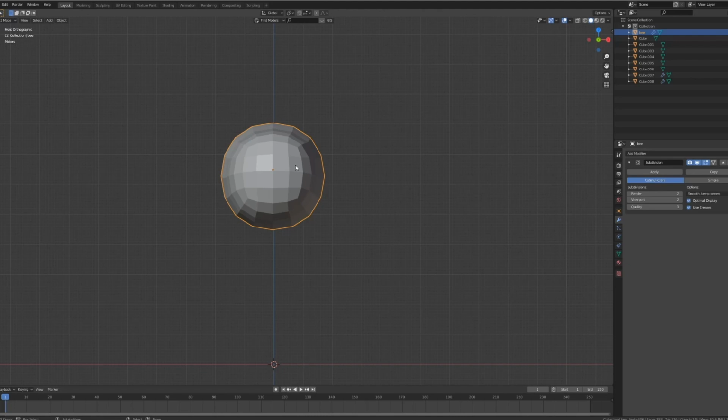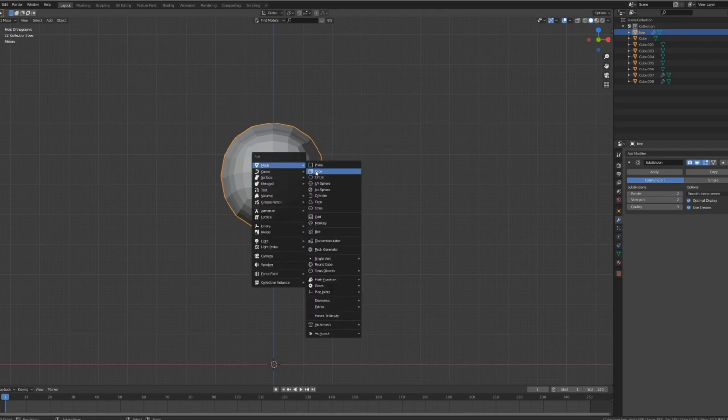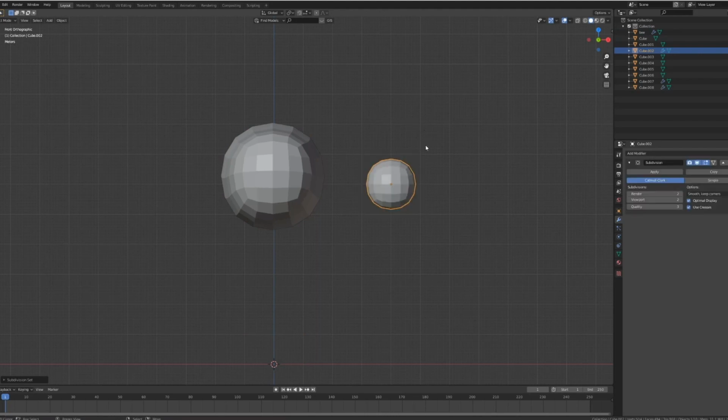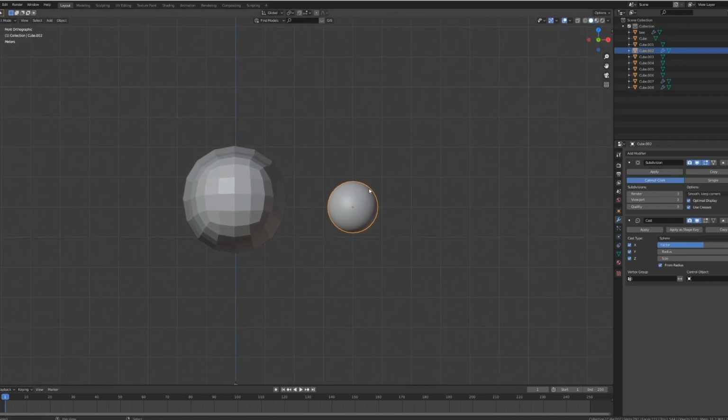Now we're going to go into the thick of it. So we're going to create a cube. I'm going to add a cube. I'm going to subdivide it with Ctrl+2, so I get multiple subdivisions. I'm going to increase the render and viewport to 3, and I'm going to add a cast modifier with a factor of 1, so I get a perfect sphere. W to shade smooth, or F1 and search for shade smooth, and this is going to be my eye. Now at this point you can ask yourself, what should the eye look like? You can help yourself with, let's say, the 3 category division.